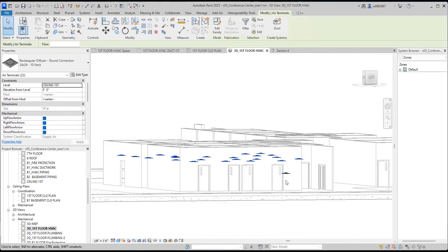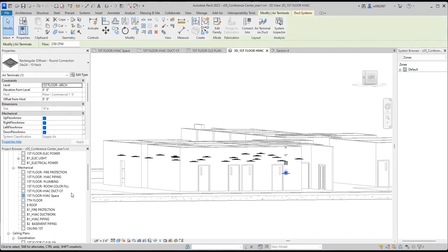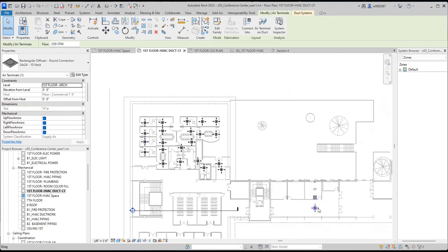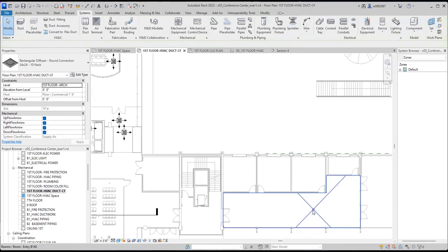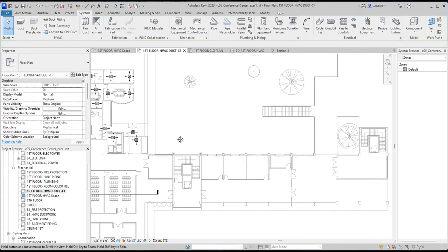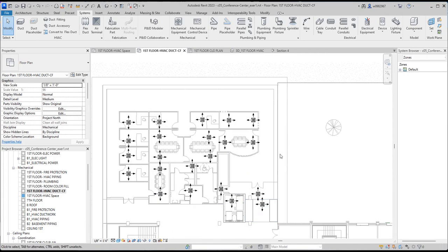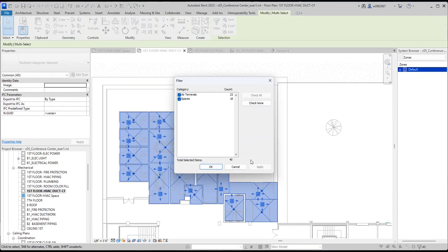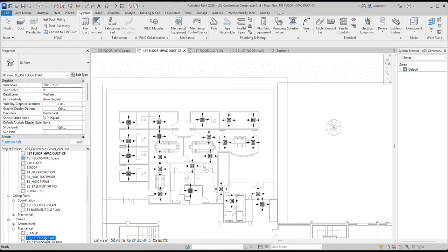They're supposed to now be on the same level. There's one here that's down. I wonder what that is. Let's go here. When I select that and then go to ductwork. Yeah, it's somewhere here. I don't know what it's doing there, but I didn't place that, so I'll just delete that. Anyway, it might be just some mistake when I was trying to move something. Okay, but that's how to fix the elevation. You can use your filter, select, and then filter out what you don't want to select. But yeah, always check the 3D of your duct.